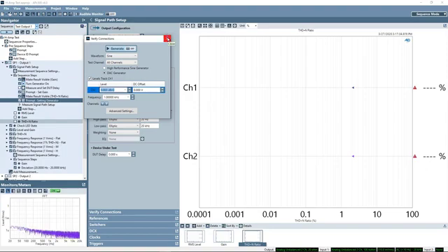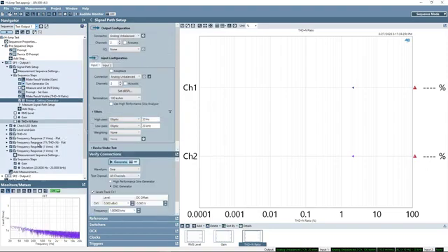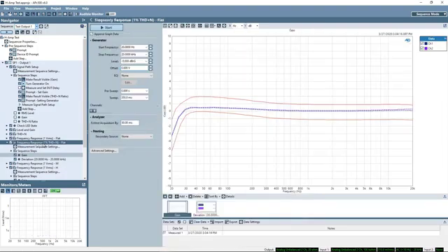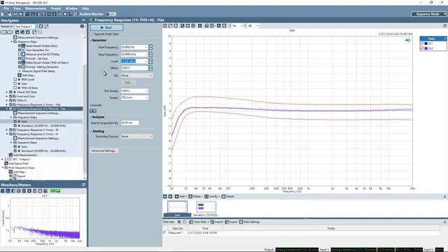Now that we've done that, if I go back to a measurement such as this one, where I wanted to measure the frequency response at 1% THD plus N, I can simply set the generator level in units of dBrG, 0 dBrG being the target required to get 1% THD plus N. That's a quick demonstration of production test mode and the production test features in the APX project file. Hope that you'll find some of these features useful, and thank you for watching.